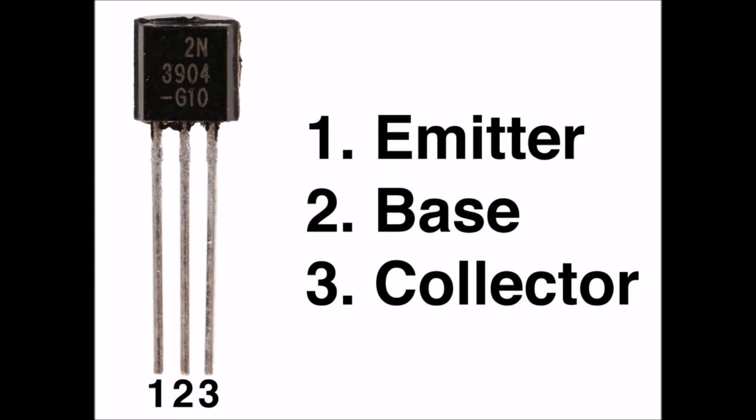The small fluctuations in base current cause large changes in the collector current. The current passes through resistor R4, producing a fluctuating DC voltage across it. The AC components of this voltage pass unhindered through capacitor C3 to the output. The circuit of figure 22.9 represents the basis for many amplifier systems at all commonly encountered signal frequencies.